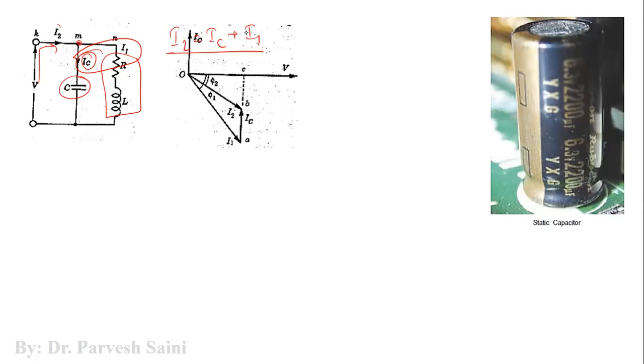Now if we draw the phasor diagram here, so it is the voltage that will remain same, because the voltage across capacitor is V and the voltage across this load is also V, because it is a pure parallel circuit, right? Now earlier the phase difference between V and I1 is, let us say, phi 1. Now by adding a capacitor in parallel to the load, what has happened? The phase difference between the voltage and the resultant current, I2, has reduced,